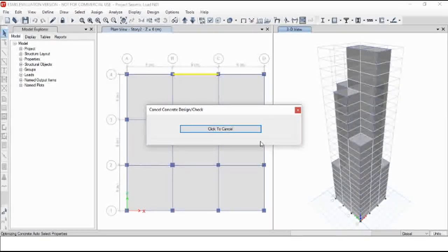The design check is under progress. The model is currently being checked for the design flaws, and just like the previous case, it would be reiterated if any member fails to change their sections to the next higher ones from the auto select beams and columns menu.